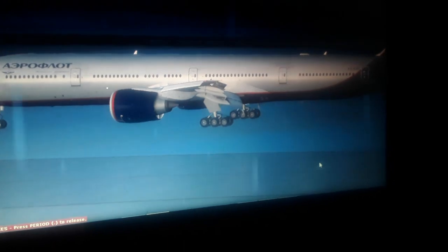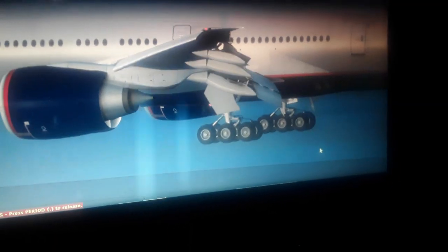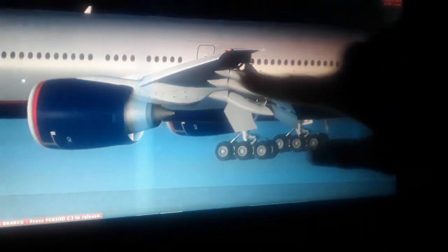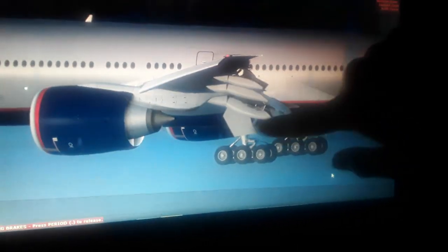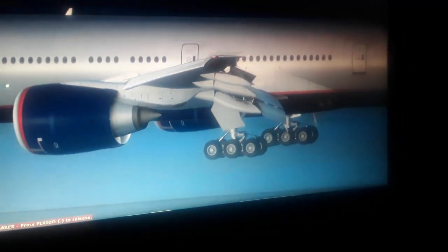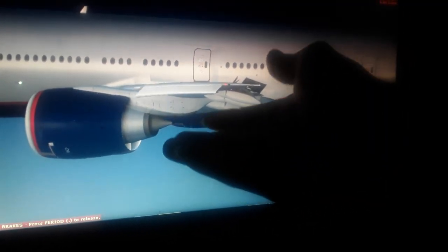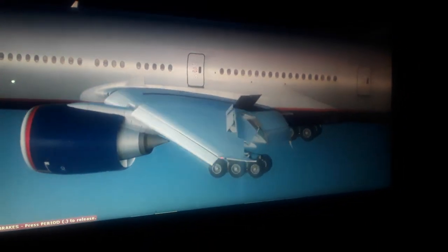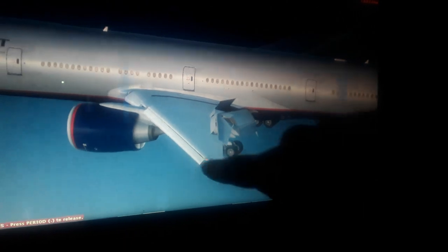Also you can see the wings that produce the lift for flying. You can see the bottom surface of the wings is more flat, so the airflow of the air mass is moving slower below the wing. So the air has higher air pressure below the wing, and this creates an aerodynamic lift that pushes the aircraft up into the air. So we have positive air pressure below the wing.